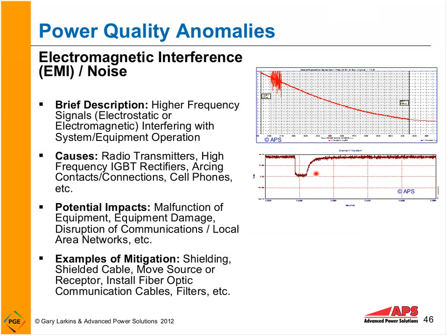They were actually causing the modem to pick up the phone line, and then hang it up. So you hear this click, click, click, click, click because of the high frequency noise. This problem was solved not by reducing the high frequency noise, which would not have been easy to do, but by switching to a different modem manufacturer. Simplest solution: find out what's working in the facility and change out to that manufacturer's product. Problem solved, inexpensive solution. So there are different sources of mitigation down here, shielding, etc.